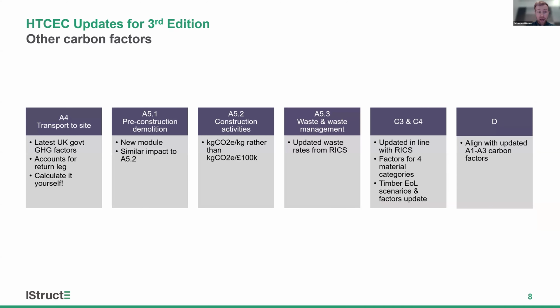Changes to other carbon factors. So there are some changes to the A4 carbon factors using the latest government greenhouse gas reporting factors. It accounts for the return leg, but we always recommend the most accurate A4 calculation: calculate it yourself based on a first principles calculation.